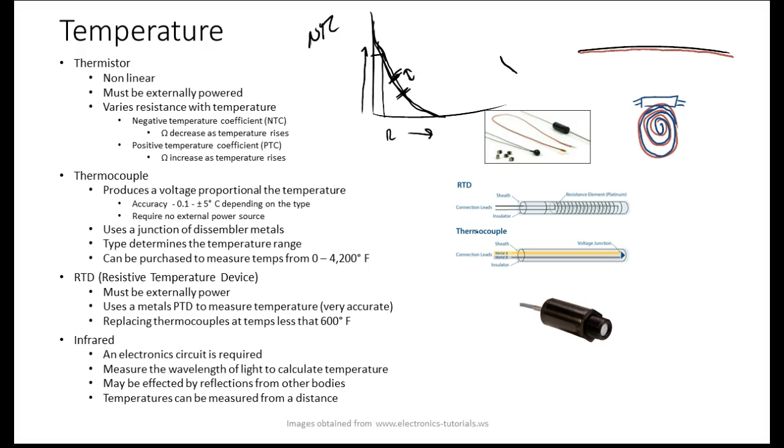And if the motor tries to pull too much current over time, it takes a little time. That's why your circuit breakers, when they pop, you've had an overload, right? You understand? They don't pop when the overload occurs, but it had an overload. So I need to add bimetallic strips to this because they're very, very popular.